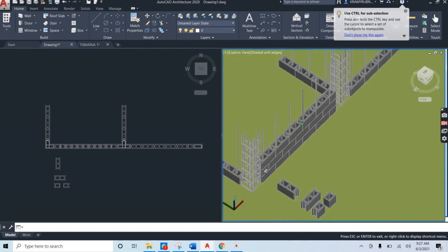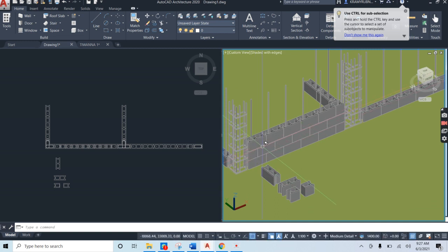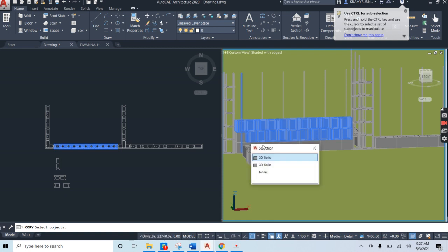Like I'm saying, you may choose to lay your blocks individually, or you might choose to just install them as complete rows. I'm going to just, like I said, in the interest of time, go ahead and copy all the blocks I am going to be needing to complete my other half of this wall. So allow me a second and let me copy these blocks. Oops, I don't want that steel. Let's release the steel so I can select this block.